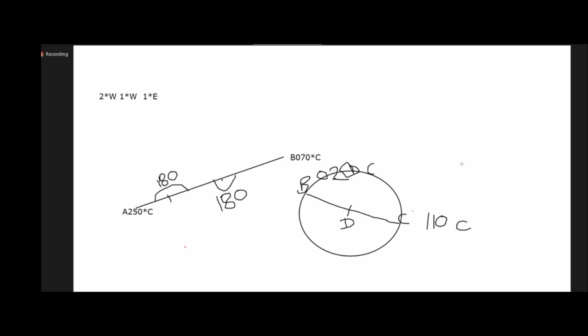How do we find that? Yes, draw. 020 means which side? From the vessel, yes, like this is your 020. 110 will be like this. It will be south. It will be south of the line. Sir, we have to see it with respect to the line? Yes, with respect to the line. Bearing is from the vessel to the lighthouse. Your vessel is south of the line.